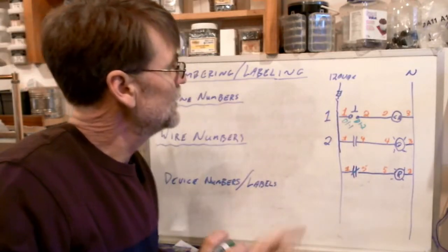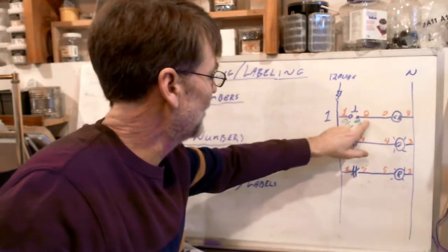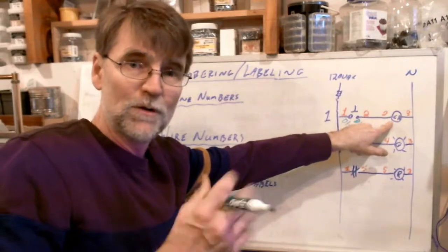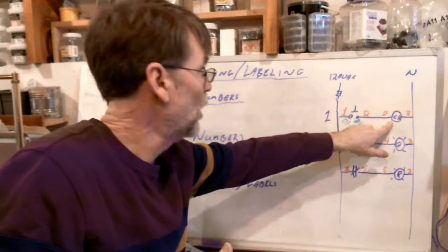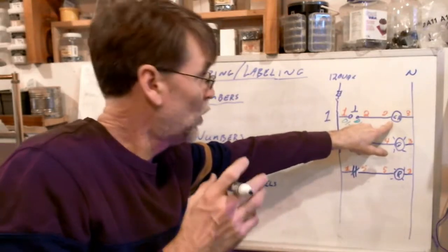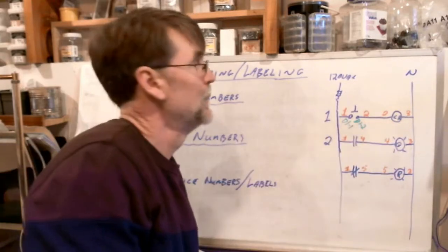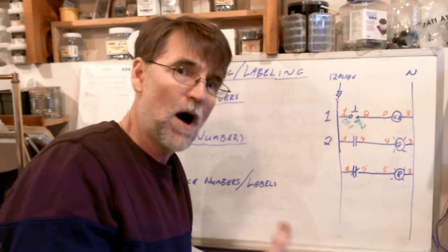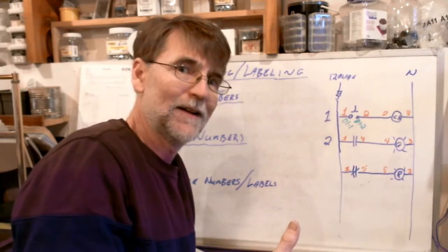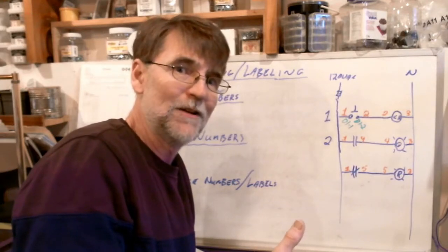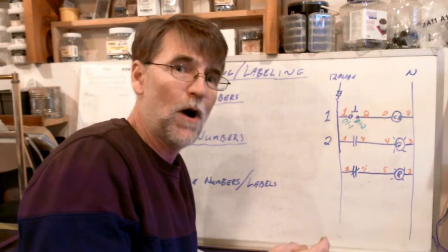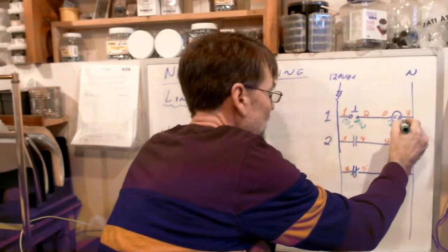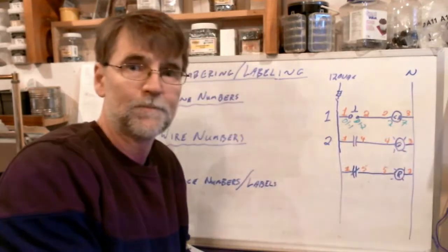The other thing, let's follow wire number 2. So this is the coil of our cube relay. For those of you who were with me last year, you already know what pin numbers on that cube relay the coil is attached to. I'm going to pause, let you guys dig back into your memory banks. Can anyone recall that it's pins 2 and 7?